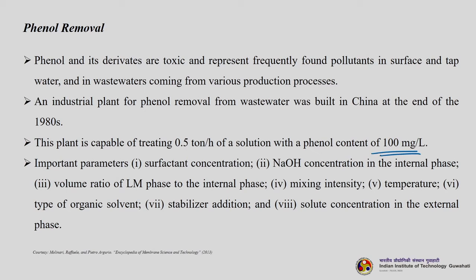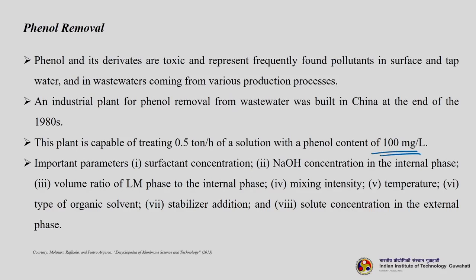So, important parameters are surfactant concentration, sodium hydroxide concentration in the internal phase. Sodium hydroxide is the stripping phase that will finally take the phenol inside it and will trap it, and it will make sodium phenolate basically. Then volume ratio of liquid membrane phase to the internal phase, mixing intensity, temperature, type of organic solvent, stabilizer addition, solute concentration in the external phase. So, these are the parameters which are all optimized for this particular plant.